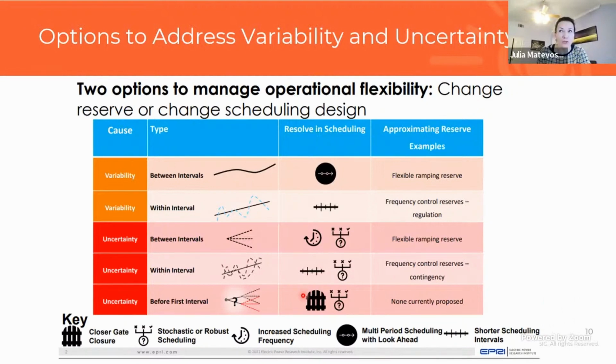And by shorter gate closures, I mean, say, for example, ERCOT runs economic dispatch in real time every 5 minutes, and it's at the top of the 5-minute interval. And to run the dispatch for the entire ERCOT system takes about 20 seconds. And so by the time the decision is made, you don't see much of the change happening on the system conditions. So you're pretty well set with these dispatch decisions.